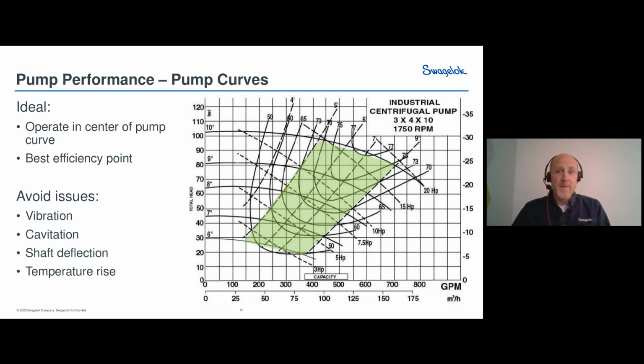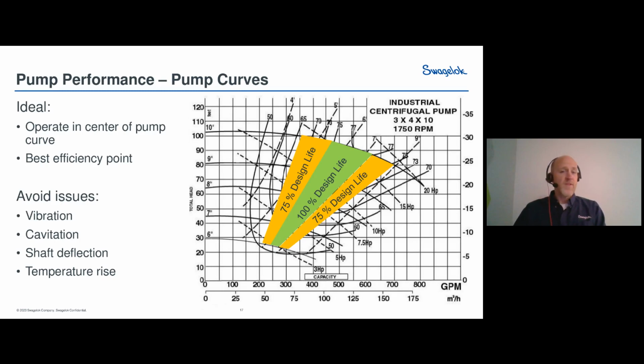So when we're looking at a pump, we really want to stay in that middle because that's going to allow us to achieve as close to the design life as possible. So theoretically, if we were right down the middle, maybe we could achieve 100% design life. If we're a little bit farther out away from the middle, maybe it's only going to be 75% design life. And again, this is really only for illustrative purposes. I'm not saying if you're a little bit off center that you're going to necessarily degrade your performance by 25%, or in this case, 50% if you get farther and farther away.